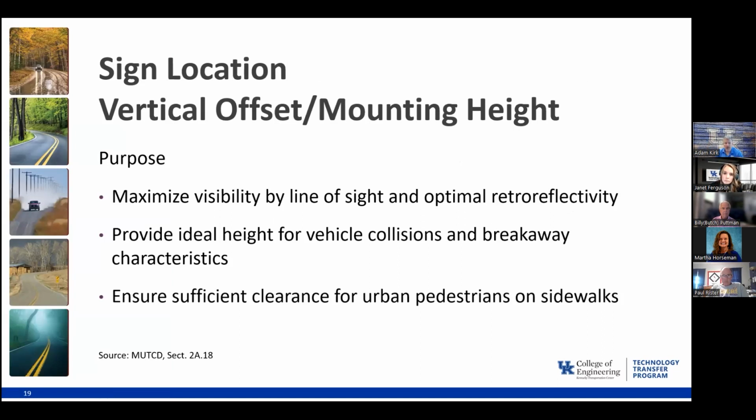and so what we really want to do when we're talking about our vertical position is maximizing the visibility of it. So we want that sign up so the drivers can see it, but we don't want it so far up that you're having to turn your head. You want to be able to see that sign looking out at the roadway and be able to spot that sign. Sometimes if we put it too far up, that really starts to limit the visibility as you go through there. It gets out of your headlights. So you might not be having that band of your headlights bouncing off of it and providing proper retroreflectivity through there.